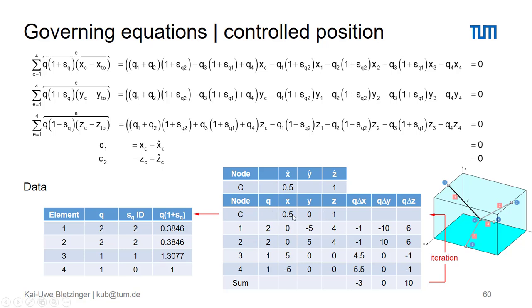With this geometry found after form finding, we can go back to determine the modified force densities by multiplying the basic force density by what you see in the bracket. I didn't give you on this slide the final values of the SQs, but nevertheless what we receive finally here are the multiplied force densities, and then we can solve for the forces, taking the modified values of the force densities and multiplying that with the actual length of these elements. At this end, everything is as before.